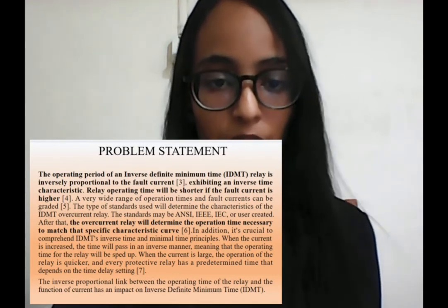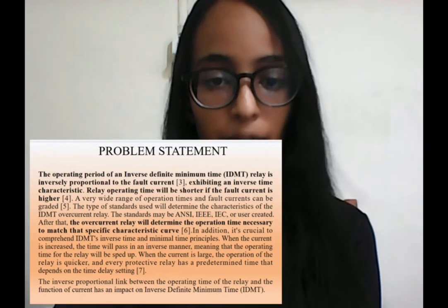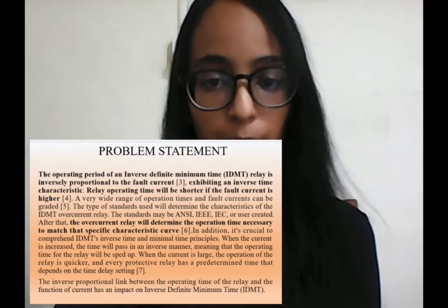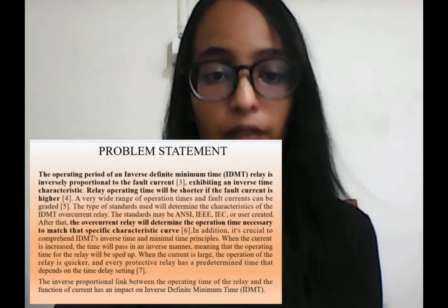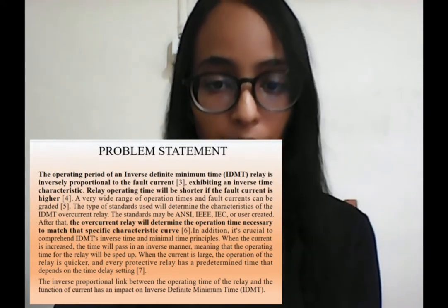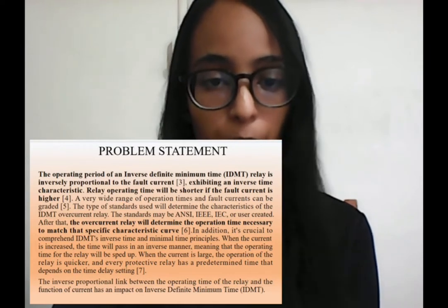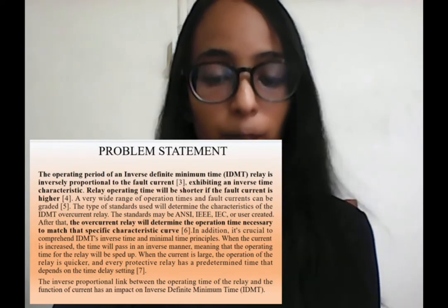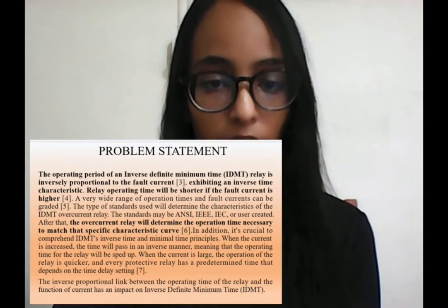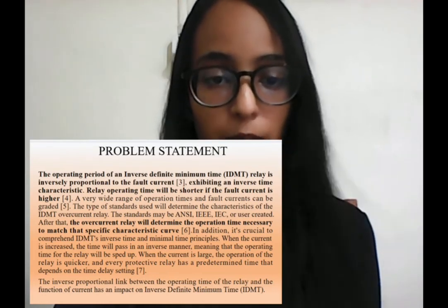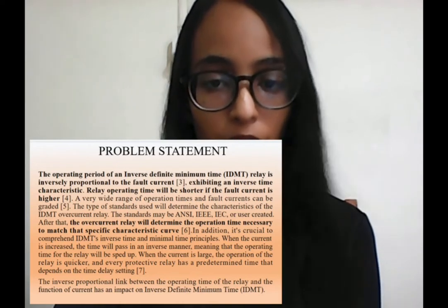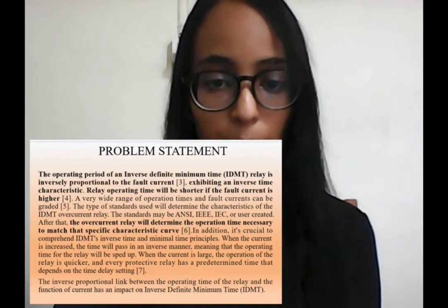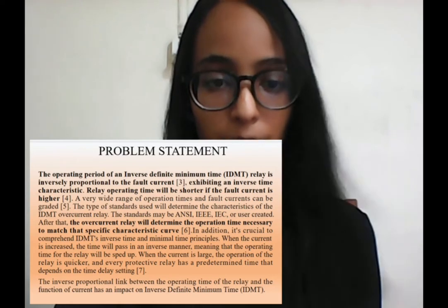In addition, it's crucial to comprehend IDMT's inverse time and minimal time principle. As the current is increased, the time will pass in an inverse manner, meaning that the operating time for the relay will speed up. So when the current is large, the operation of the relay is quicker, and every protective relay has a predetermined time that depends on the time delay setting. So the inverse relationship between the operating time of the relay and the function of the current has an impact on inverse definite time.